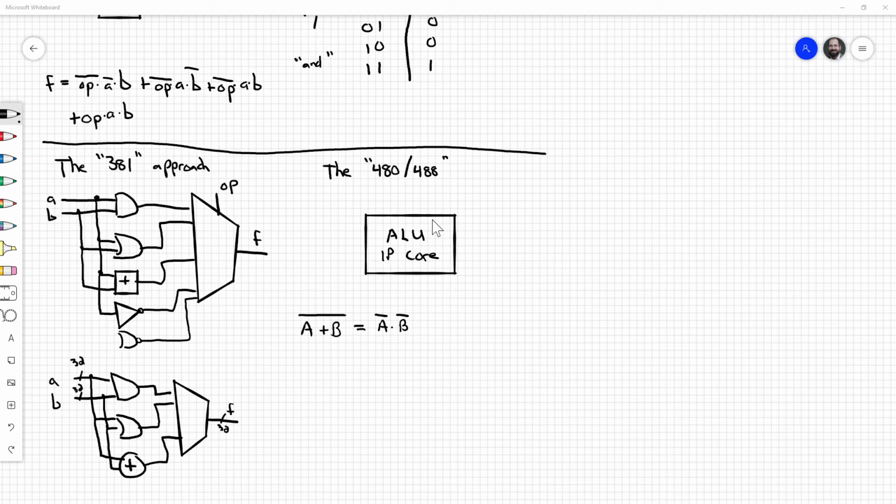But from the lookup tables perspective, AND gate, OR gate, NAND gate, it doesn't matter. It's all the same. It's all a truth table that gets directly encoded into my circuit. So it should be very, very similar when we're mapping to an FPGA at least. And even if we weren't, if we were doing explicit gate-based logic minimization, it should be really, really close, if not identical, when the synthesis tools get their hands on it.